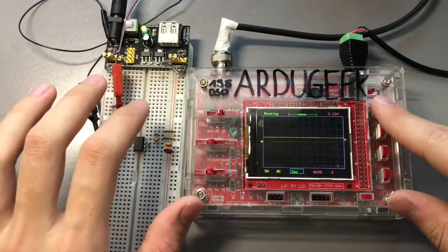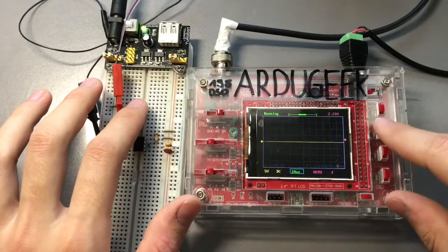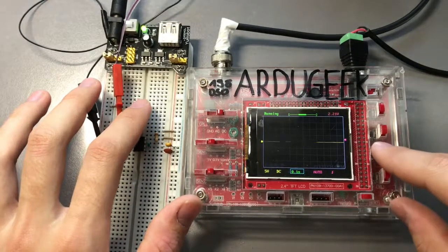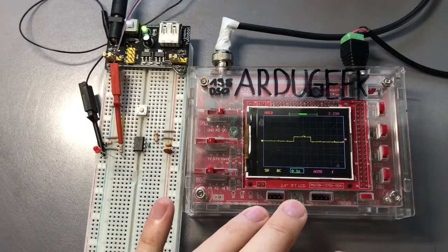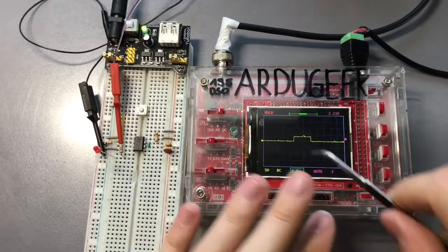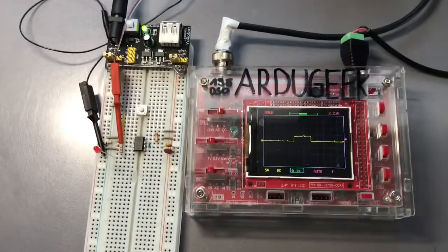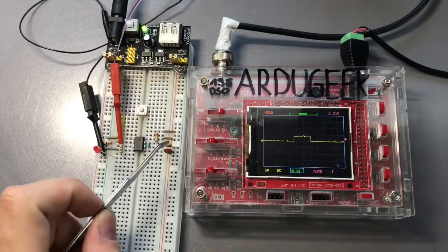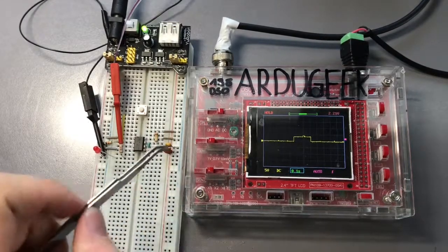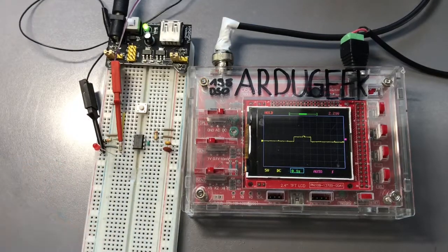What I mean by manually, if I increase the time base like that, just hop on, and it is like 0.3 seconds, which is the normal cycle that we had before in our configuration. So as you can see, it's working pretty well. The cap that I replaced last time from 10 microfarad to 1 microfarad is now 1 microfarad like before, with a 220 kilo ohm resistor.